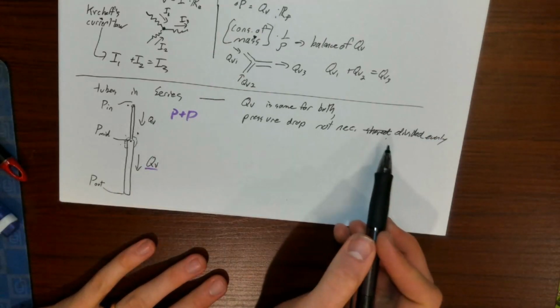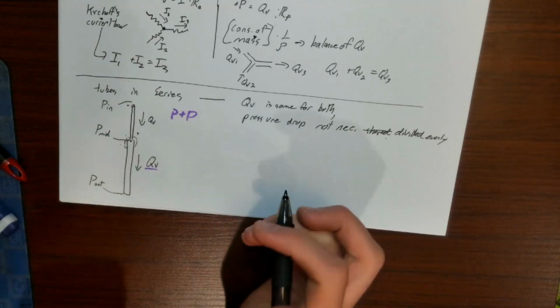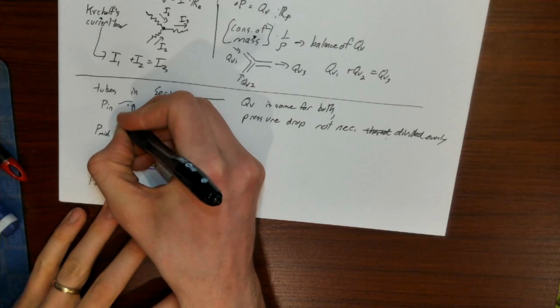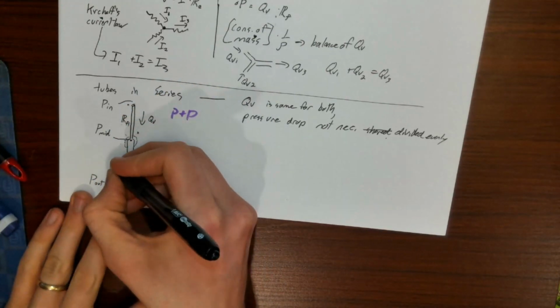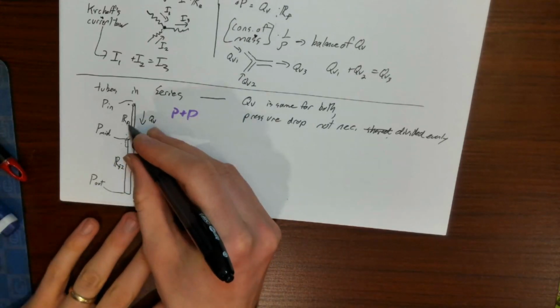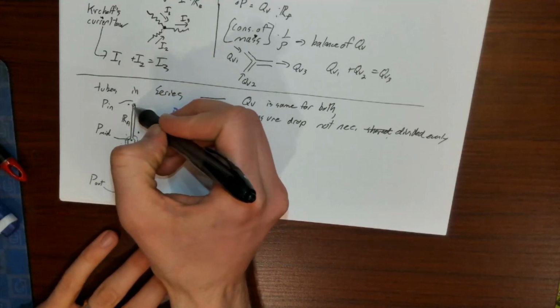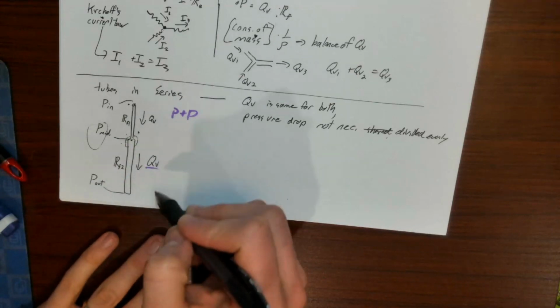In fact, the drop is proportional to the 2 resistances that exist. So a lot of times we might say, if there was some fluidic resistance from this first section and some fluidic resistance of the second section, could I come up with some equivalent resistance, without bringing in this middle pressure and complicating things?